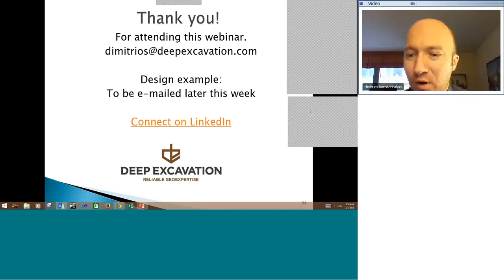There's a question: how do you account for that in a nonlinear analysis? Actually, we gave some details in the first webinar, and that's based on how you model the soil elasticity. If you watch the first webinar, you can use different soil models, and depending on how you model your soil springs or your finite element analysis, you can have soil springs that are nonlinear, and you can also have finite elements, discrete triangles or rectangles or whatever else you use, that have nonlinear response.